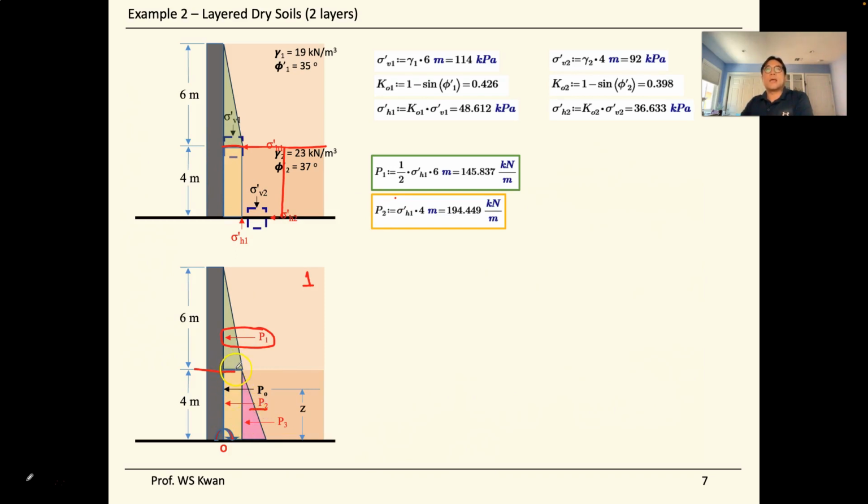This rectangle, the force from this yellow rectangle. Similarly, we do this pink area here, this triangle representing the soil on the second layer to the lower portion of the wall. And since when we isolate it, we just look at a single layer of soil, then it's a triangle effect, because we just talk about the effect of the soil on the same level or the same layer.